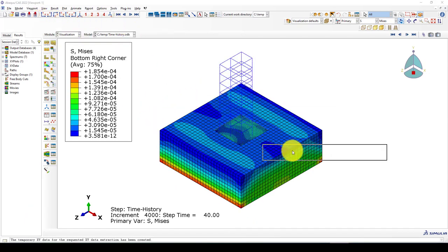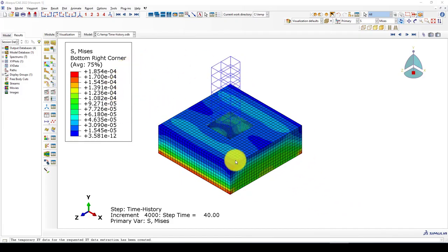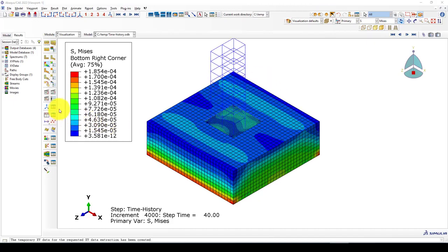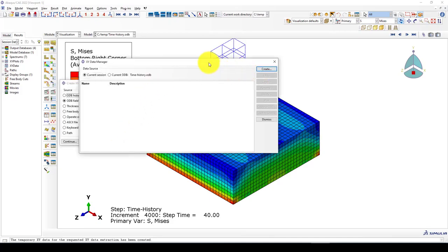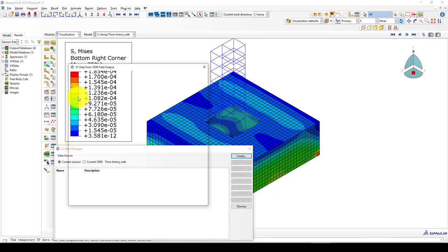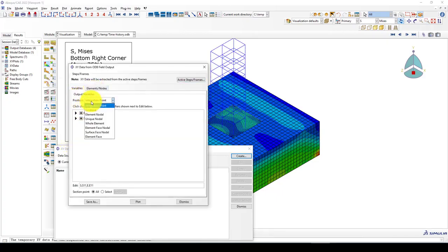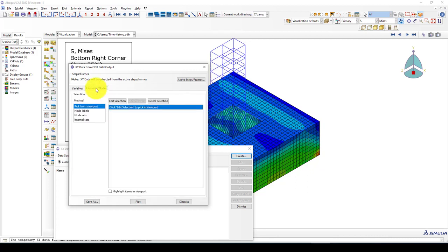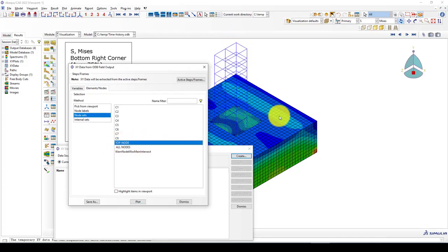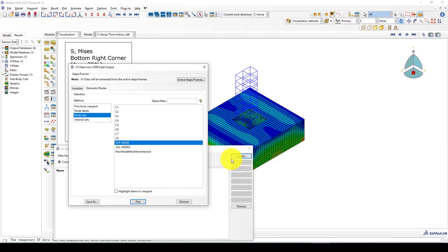and now here is the result, and we want to interpret some of the data. So this is the entire stress, one mesh stress, and you can just go to remove one part and see another one. But I just want to create some output. List the first output. I want to see the top beam displacement. Go to here and go to unique nodal and node set. I have called top node set here, that point. I'm going to plot this one.